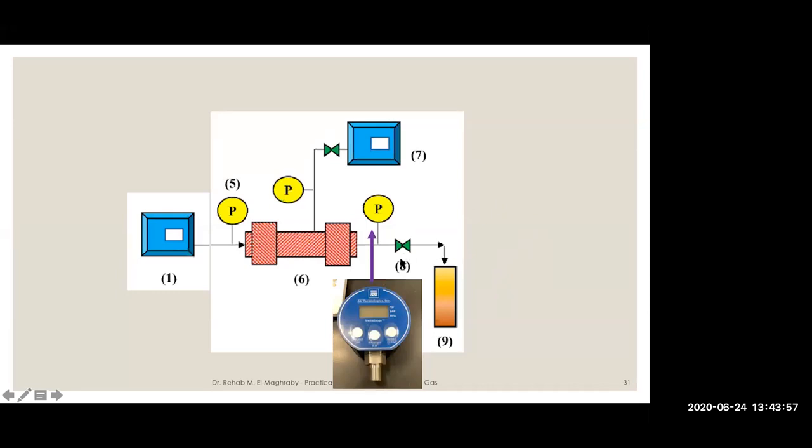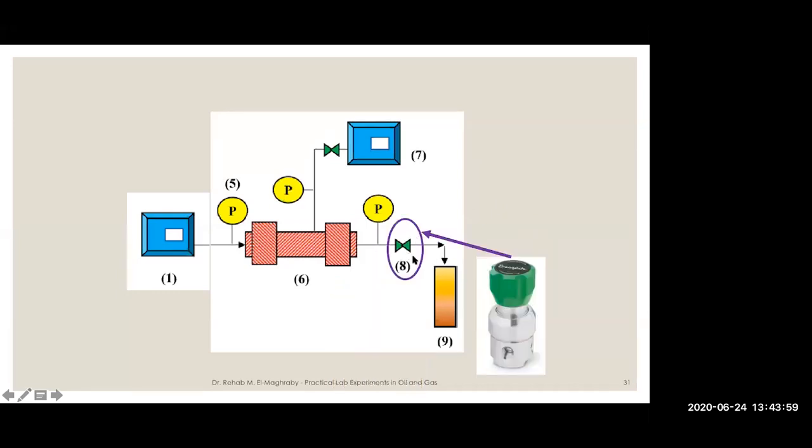At the end, there is a back pressure regulator where you can govern the delta P. You can close this valve a little. If you close it somewhat, you will get a high pressure here, and you cause your system to have a pressure build up. So you can adjust the pressure of the system here, and you have to maintain a certain pressure and a certain pressure difference. This is controlled through a back pressure regulator.